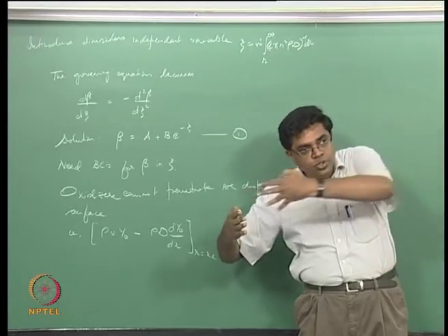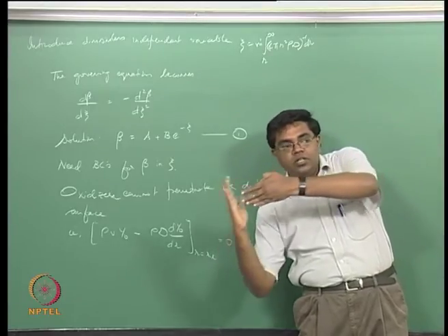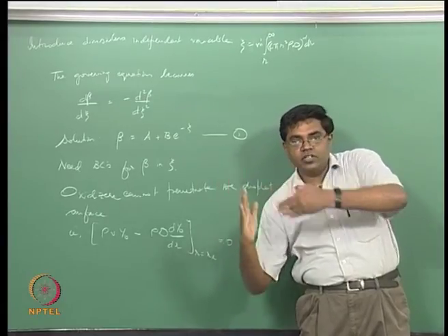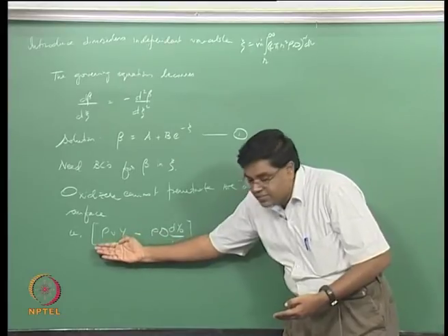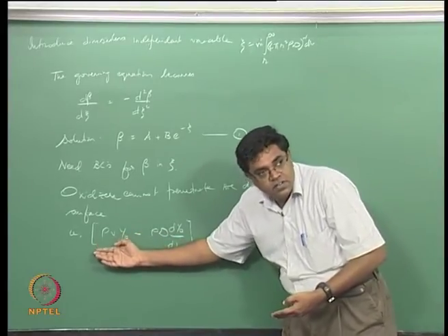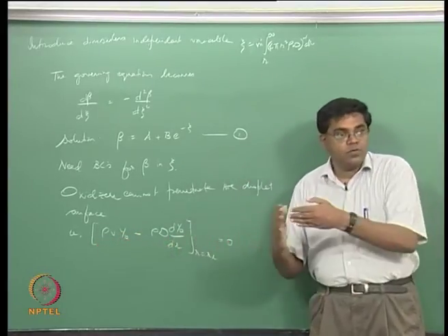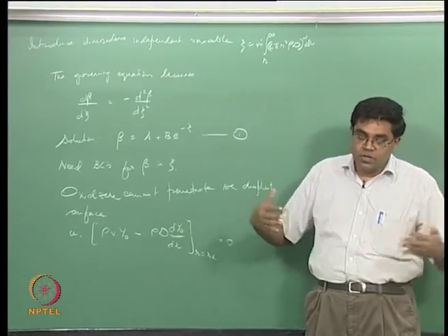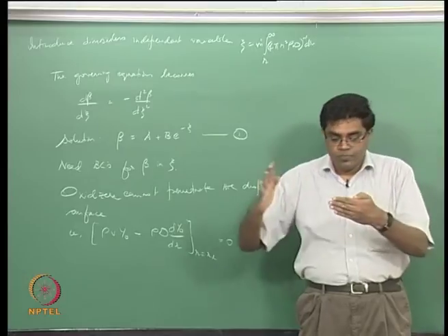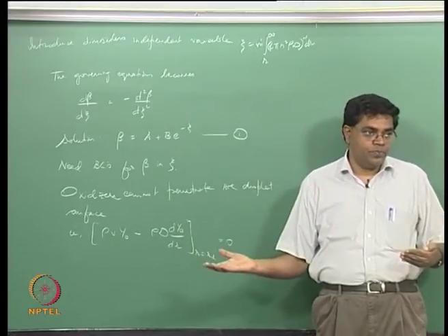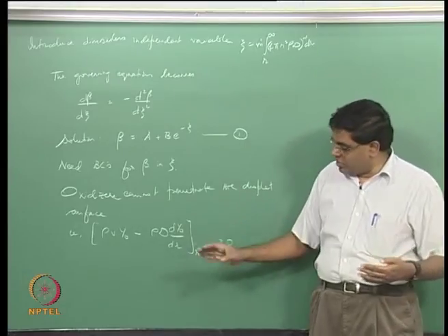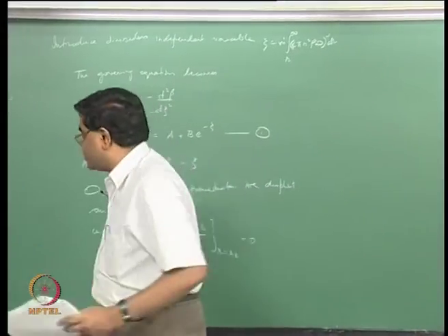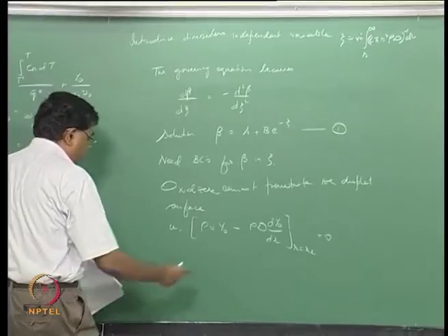So the diffusion is trying to match the droplet regression. The droplet regression in terms of convection of the oxidizing gaseous species is this, and this is the diffusion. So this basically states that the diffusion can happen just as much as the convection allows, due to the droplet surface regression. This is essentially the boundary condition here, and this is in terms of r,